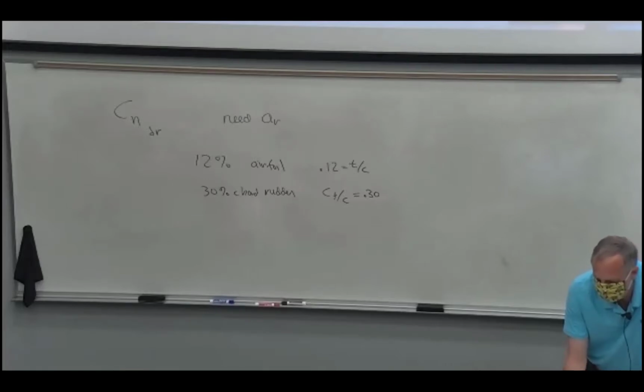So there's the chart. Make sure you mark the points you picked. The 0.3 is the 30%, and you go up to the 0.12. It's because of 0012, and you go across and you should get like 4.5 something. So make sure you show the chart, show the point, because you're going to get credit for showing the point on the plot.